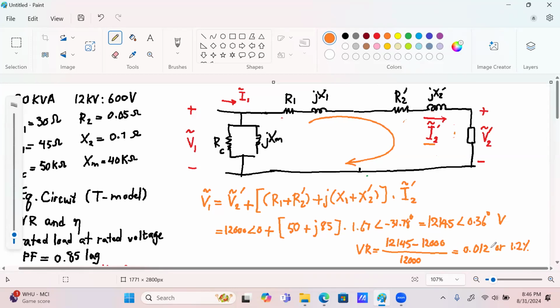As you can see, there are a number of equations that you have to write to solve these equivalent circuits of transformers, but because all transformers are modeled in either of the two ways that I discussed today, you basically have to use either of those two sets of equations. So it doesn't really matter what values or parameters I give you, you still have to either write and solve 2 KVLs and 1 KCL for the T model or a single KVL for the simplified model. So hopefully this gives you a better insight into how you would solve a transformer, and you feel more comfortable with these concepts that we talked about in class.